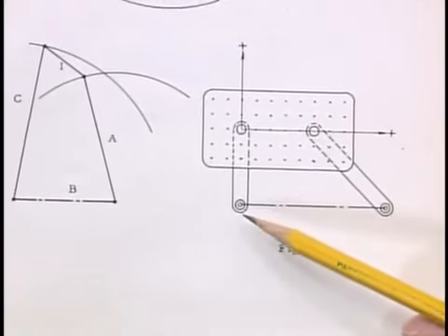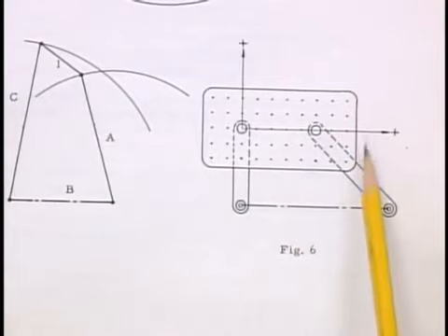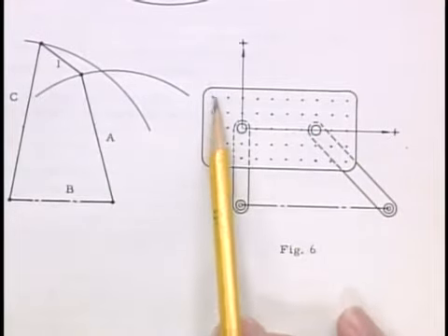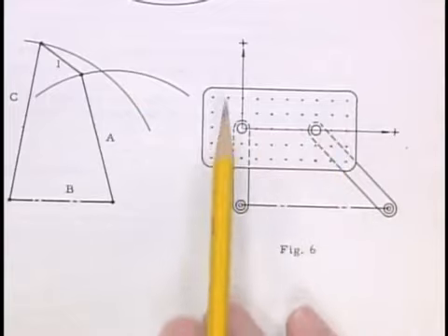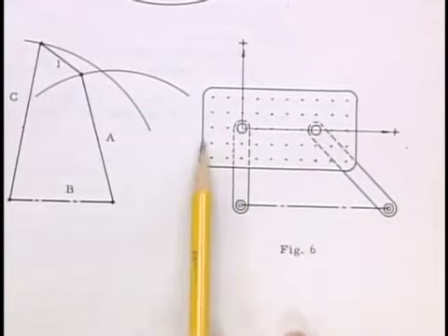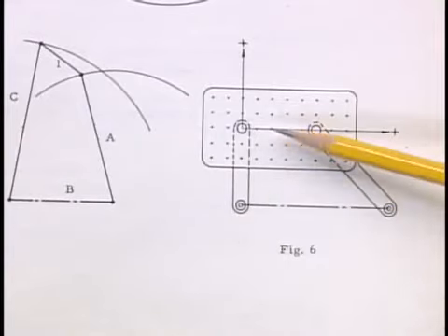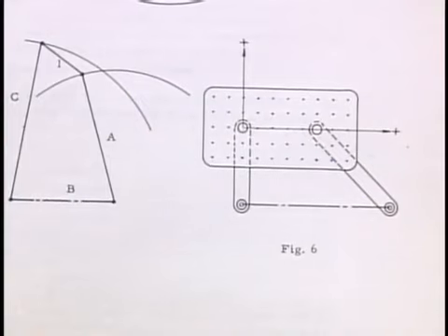So here you see link 2, link 4, and an expanded coupler, much like my cardboard model, which is peppered full of holes. And they typically have 5 rows of 10 holes each on each linkage. And they're going to iterate the link dimensions, i.e. the link ratios, as you go through the book.